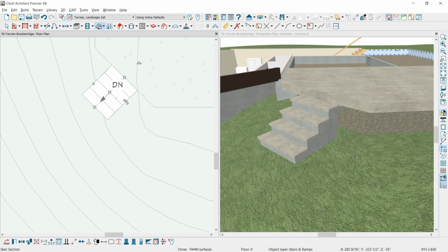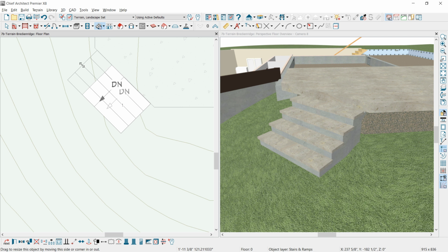And in the plan view, we'll go ahead and pull these stairs out so they almost fill the entire area. I'm going to put some walls underneath of here so they almost fill that whole area of the porch, and then we'll just snap that into the center place.